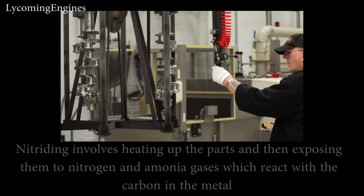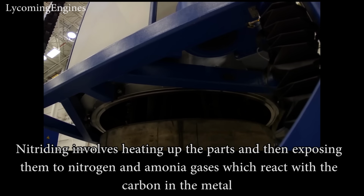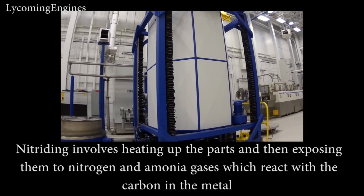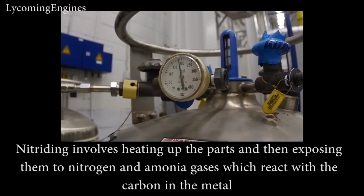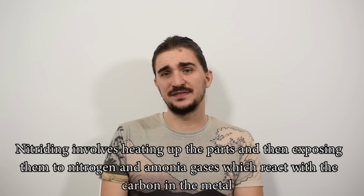Now, nitriding is the more common process when it comes to surface treatments, and it involves the crankshaft being heated up in a special furnace and then exposed to nitrogen and ammonia gases. These react with the carbon on the surface of the crankshaft, thereby making it much harder.